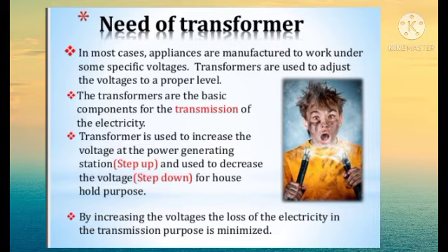Transformers are used to increase the voltage at the power generating station and to decrease the voltage for household purposes. By increasing the voltage, the loss of electricity in transmission is minimized. Increasing the voltage at the power station is known as step up, and decreasing the voltage for household application is known as step down.